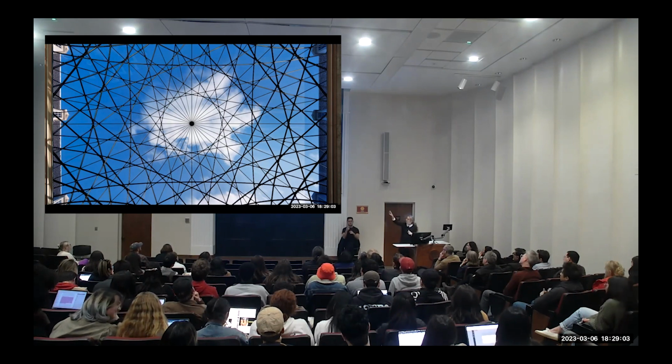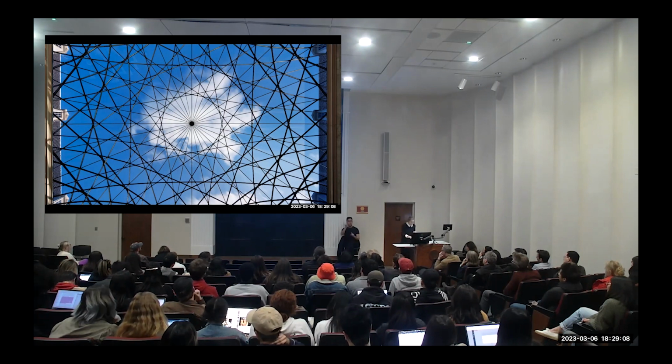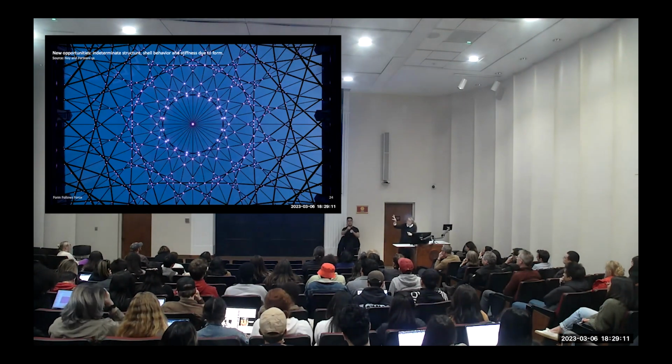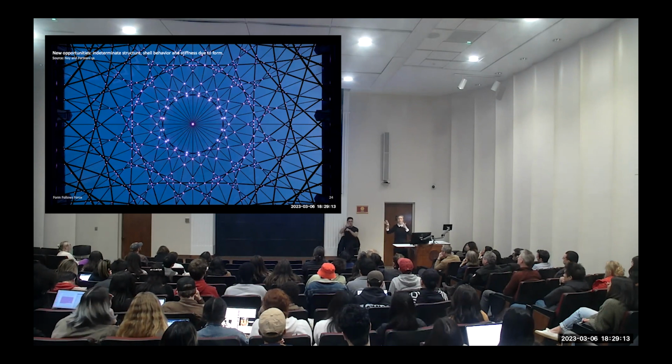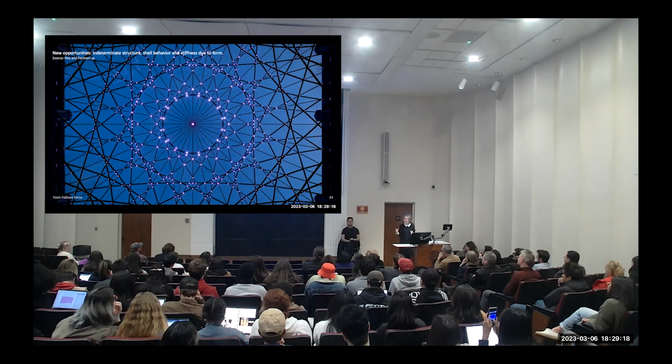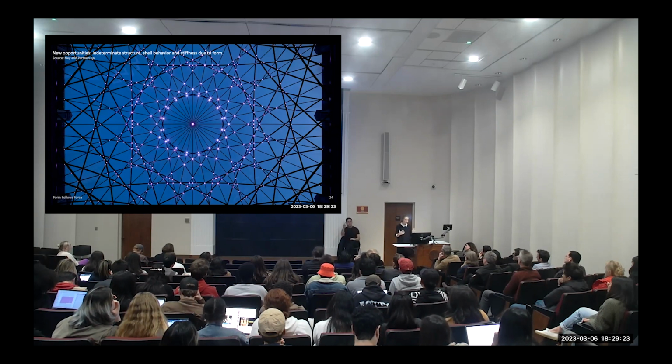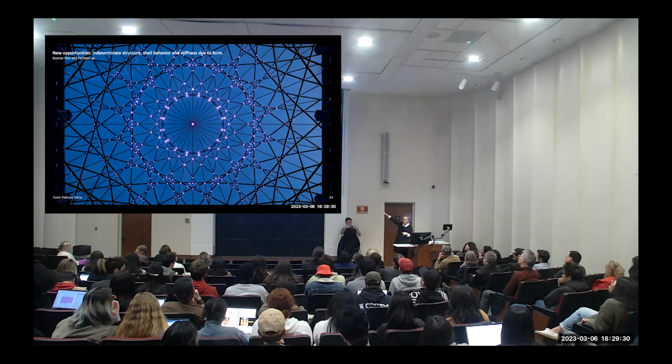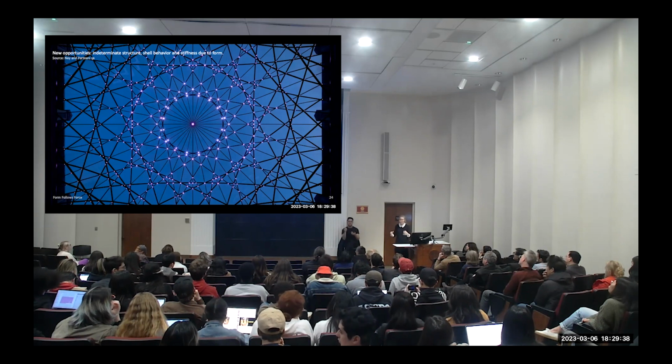The other thing that we did is at the nodes of the grid, we put in LED lights, so at night it looks like this. And the idea was that maybe then it kind of looks like you're looking at a starry sky. But while working on this project, I realized that these kind of grid shells and shell structures are actually really good. First of all, they are indeterminate structures. That means that if one of the members breaks for some reason, or if there's a hole somewhere, then the forces will find another path, right? So there's redundancy in the system, and that's generally good.